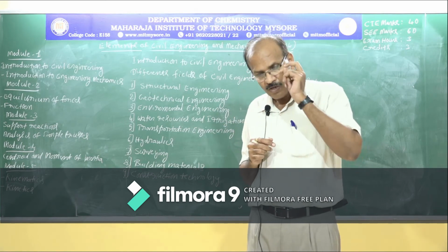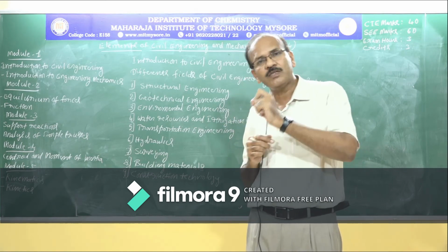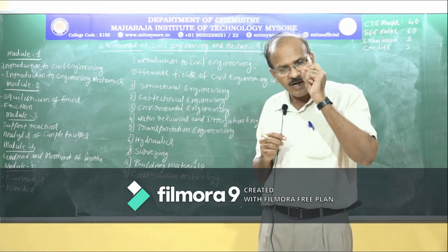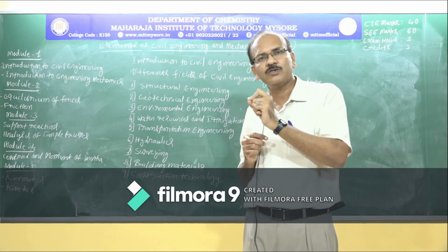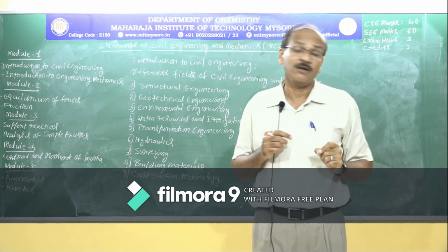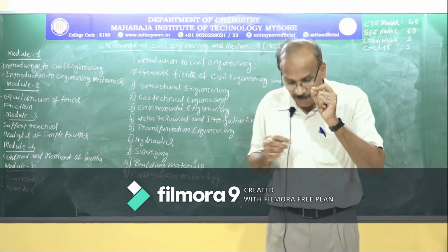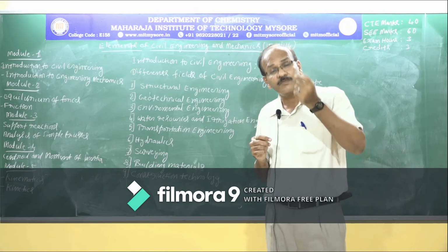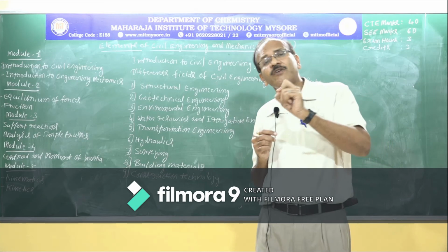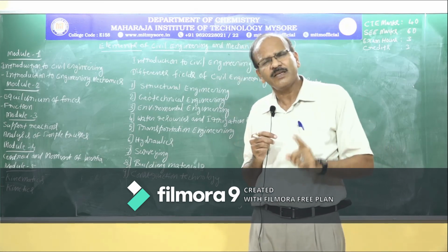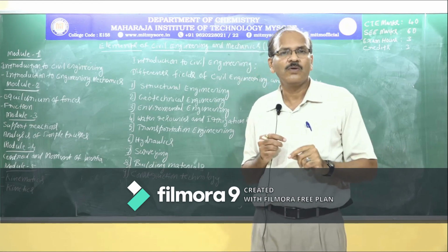We are going to do a crushing strength test by applying load on the bricks, and we are going to decide whether that brick is suitable to be used as a building material or not. Then we are going to conduct absorption test, sound test. So different tests we are going to conduct on that particular brick, just for brick alone.